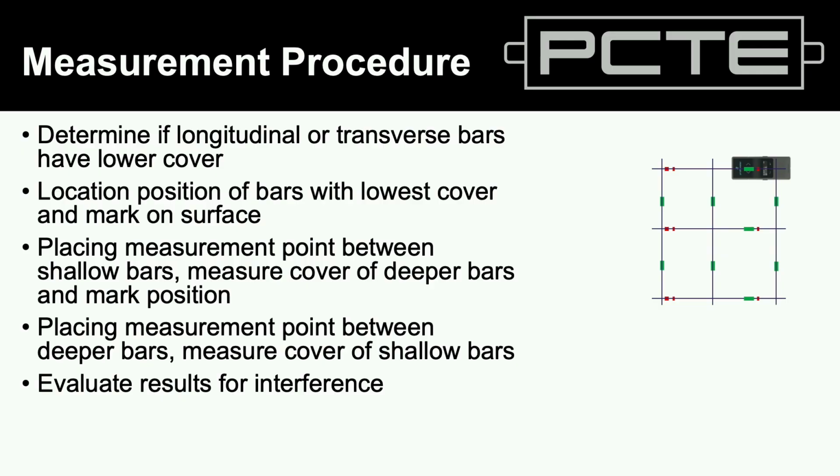Now, if I discover the bars are closely spaced or I'm maybe not getting good locating work, the first thing I'm probably going to do is go half a meter above or below my spot, because if I'm on lapped reinforcing, that normally gets me away from lapped reinforcing out in the mid-span of a mesh. Quite helpful. If ever you wonder why isn't it working, go up, go down, try and find a better spot. And if you find that you can't isolate single bars, you might need to do some investigation to discover how the spacing and layout is and put that into your cover meter so at least your numbers are accurate.